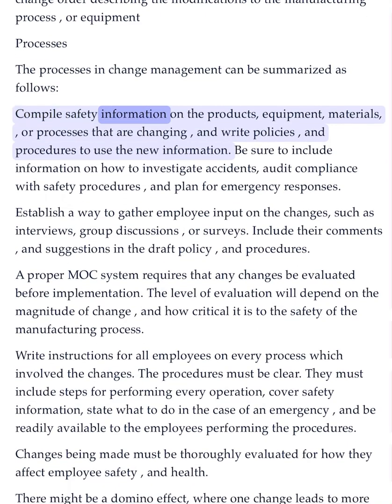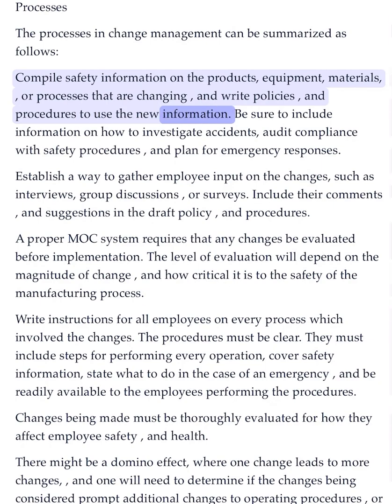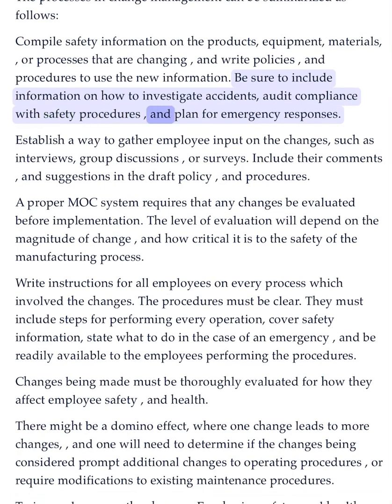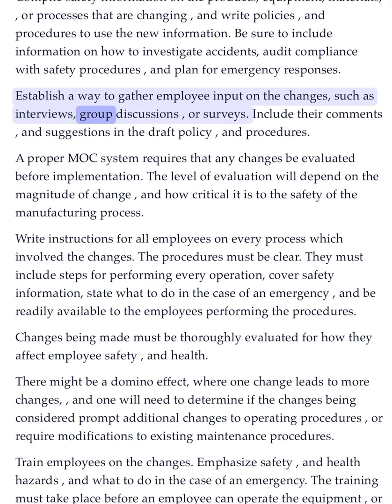Compile safety information on the products, equipment, materials, or processes that are changing, and write policies and procedures to use the new information. Be sure to include information on how to investigate accidents, audit compliance with safety procedures, and plan for emergency responses. Establish a way to gather employee input on the changes, such as interviews, group discussions, or surveys.